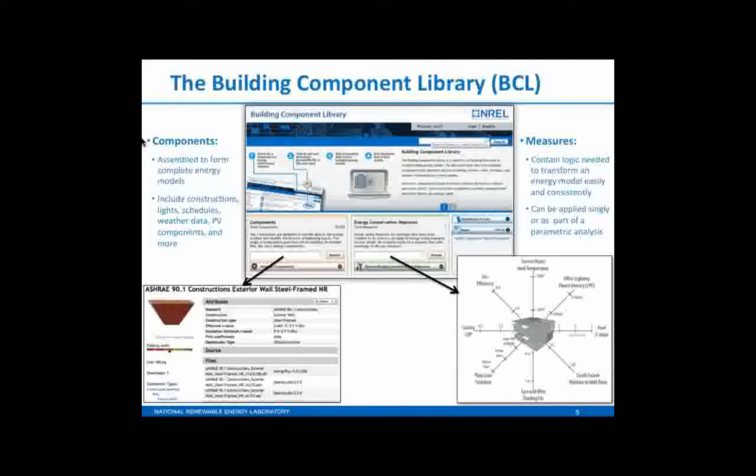And by wrapping all that stuff into a script, you enable people to repeatedly redo that same analysis, or apply it to a huge amount of building types or locations for the same building, so that your data sets are far more reliable than if a user started with what we call a seed model, like your baseline building model, and then just did lots of save-as and changed one parameter in the GUI interface, which is just an easy way to screw something up or forget something.